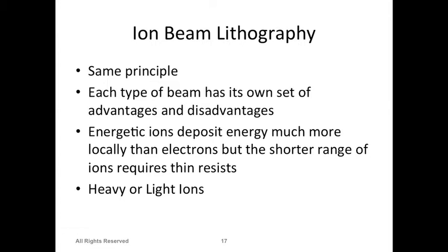The only difference is in this case we use gallium or argon ions to actually bombard the surface. And they have sometimes advantages and disadvantages. The ion beam mostly shows a better resolution. Ions are larger. You can think about it, these are whole atoms, right? Not just small electrons. So they are big atoms which are ionized. And when you bombard them on the surface, their effect is actually more localized. Why? Because they cannot really penetrate deeper inside a material because of their size.